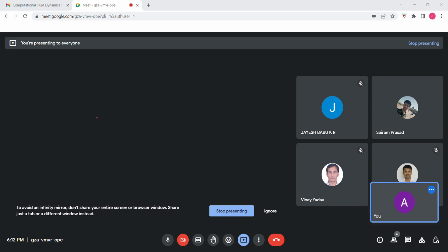The first is temperature at both ends is given. Here the temperature over here and here is given, let's call them TA and TB. The second is heat flux at both ends is given, so heat flux here and heat flux here. This is option 2. Or else heat flux and temperature at one end, that is, at one of the ends both heat flux and temperature are given. In the last option, heat flux at one end and temperature at the other end is given.